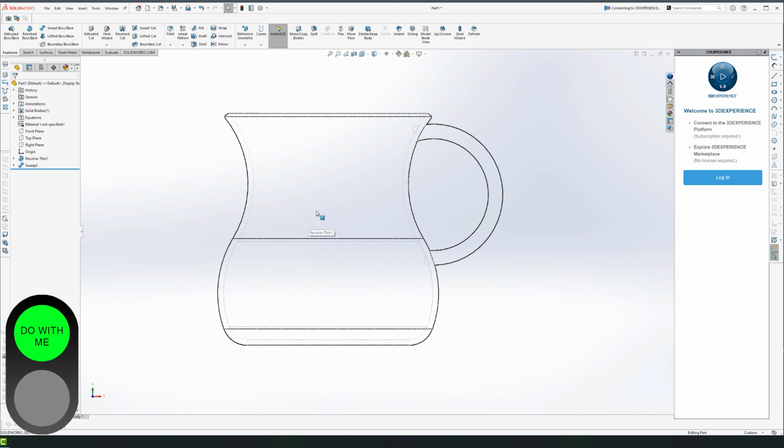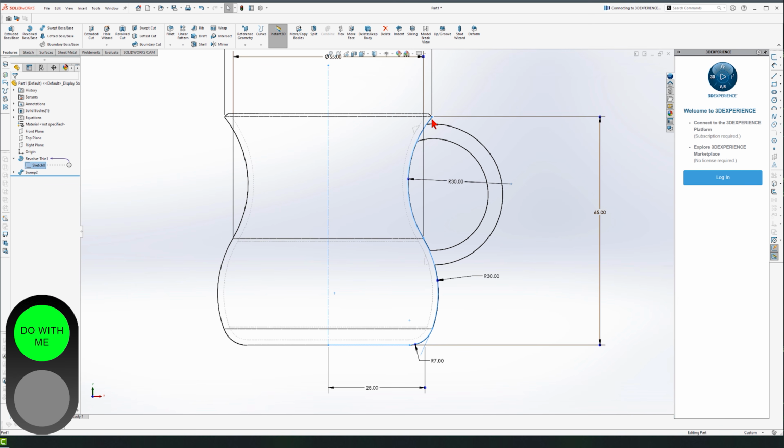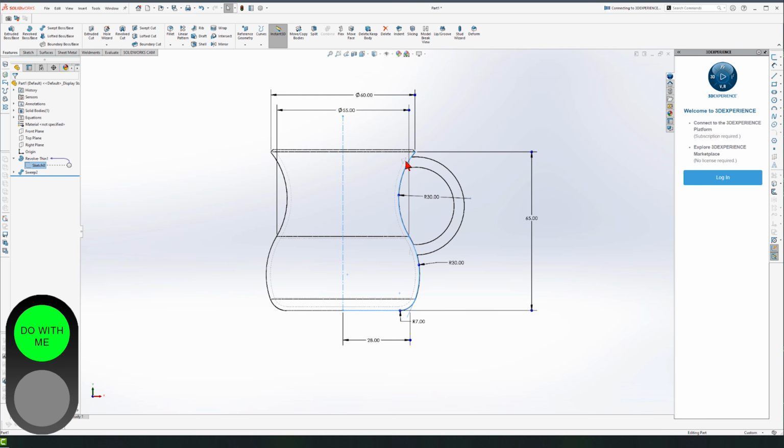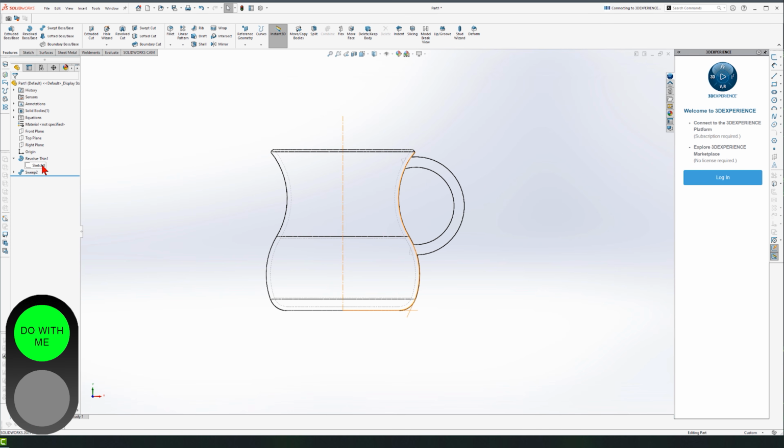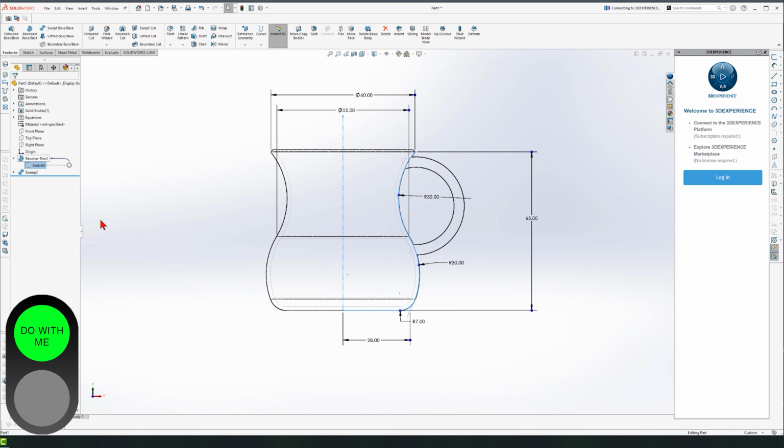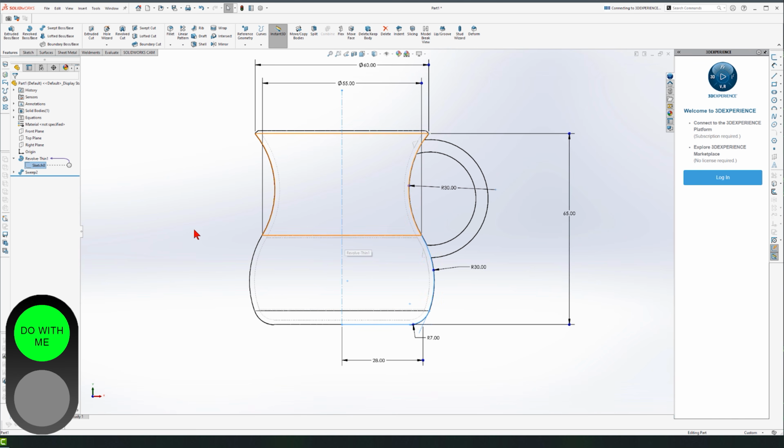What I want to do is to use the same sketch, okay, and create a negative revolve on the inside. How do we do this? If I open my Revolve, I see my sketch here. The sketch is here, but I wanted the sketch to be on the inside. And the thickness of the glass, we set it at 1.5, right? So I'm going to click on Sketch under the Revolve thin one. Just highlight it.